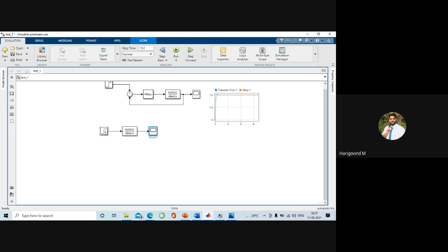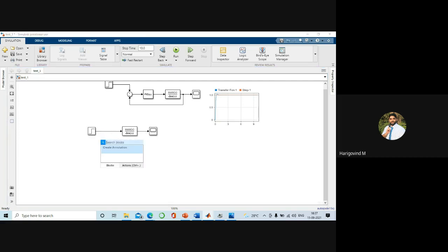We can give either positive feedback or negative feedback. To give feedback, we can either add input and output, or subtract input and output. Normally we subtract input and output so that there is an error. And when the error becomes 0, the input and output remain the same. That's how we get the desired output. We are controlling the system. So we need something known as a sum.